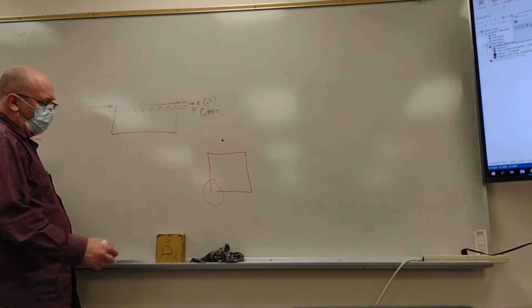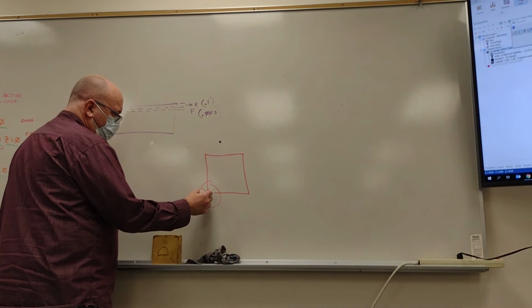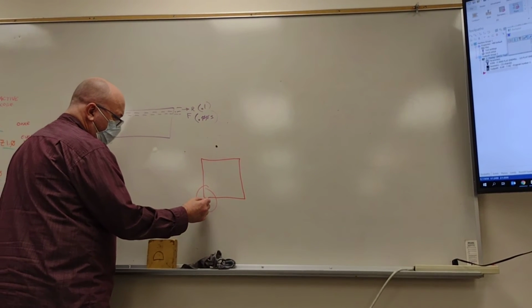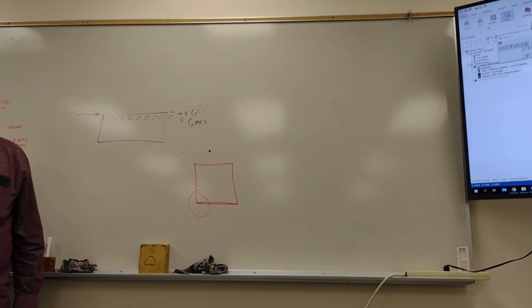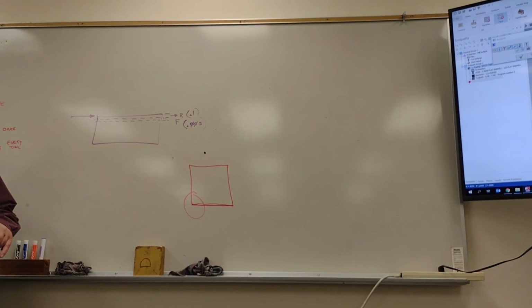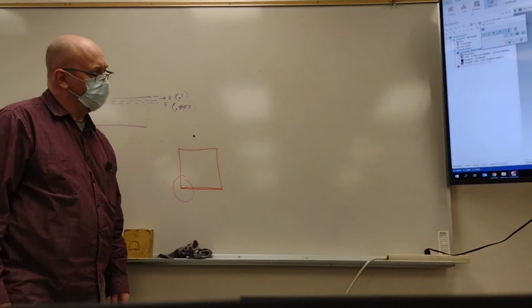And that's one of the reasons why we use that geometry from level 1 to draw over the top. If you had a double line here, it'll give it problems for chaining it. So I'll have to look at yours a little bit closer here and see why it's not collecting it.